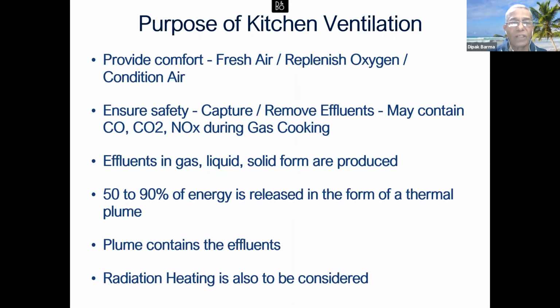The purpose of ventilation is obviously to provide comfort, fresh air, replenish oxygen, and condition the air for people's safety. Now we capture and remove the effluents. The effluents generated in kitchens will have carbon monoxide, carbon dioxide, NOx during gas cooking, etc., which we have to remove. The effluents in gas, liquid, and solid form produced during cooking also have to be removed.